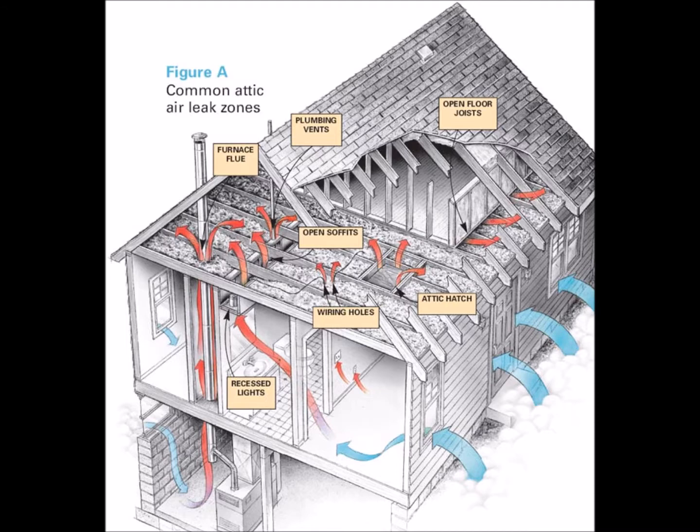We want to ensure that the air barrier functions as intended, that leaks in the building envelope and the air barrier system are reasonably controlled. The methods are generally low-tech and really make common sense. Building codes require air sealing around the following types of areas: knee walls, openings between window and door assemblies, as